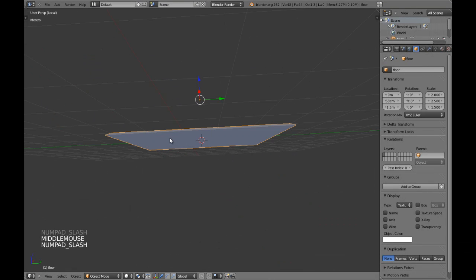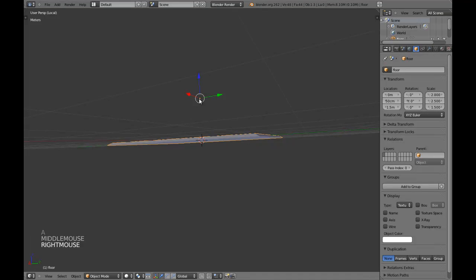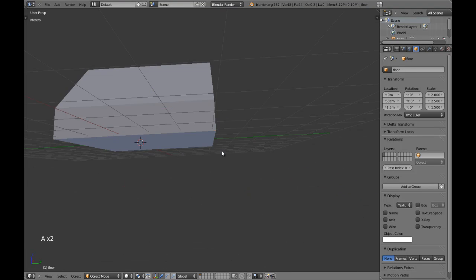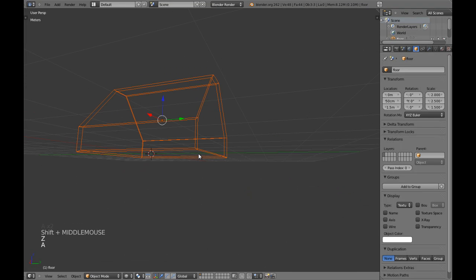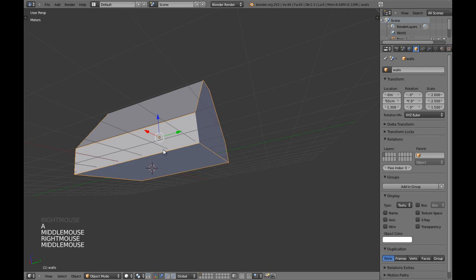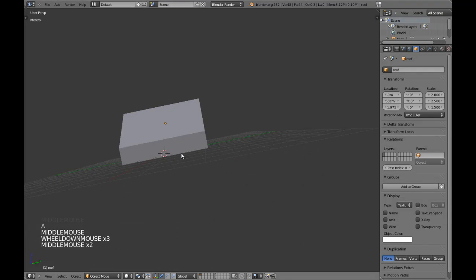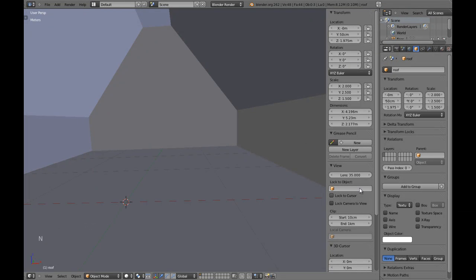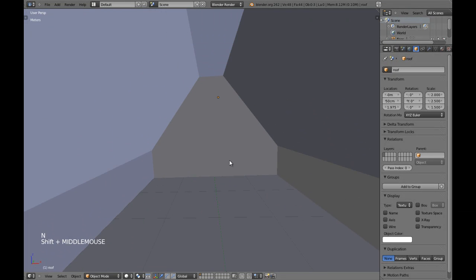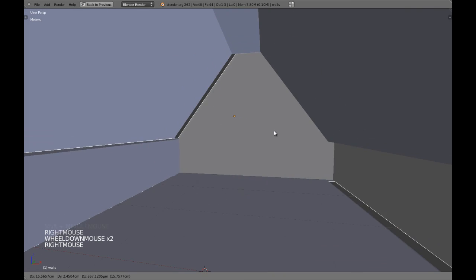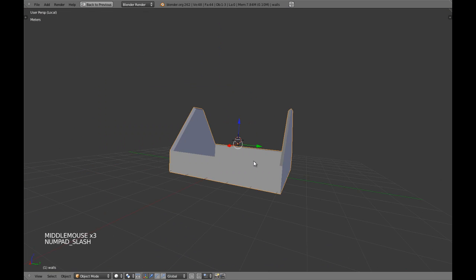Okay, when I select the floor, you can see this dot in here, orange dot. This means that this is the center of the object, so I'm going to change this by selecting everything in here, Shift Control and C, and origin to geometry. It's going to work pretty good. Now we have thickness, we have our basic shape. Now what we need to do is to create the window and the door, the space for all those things.